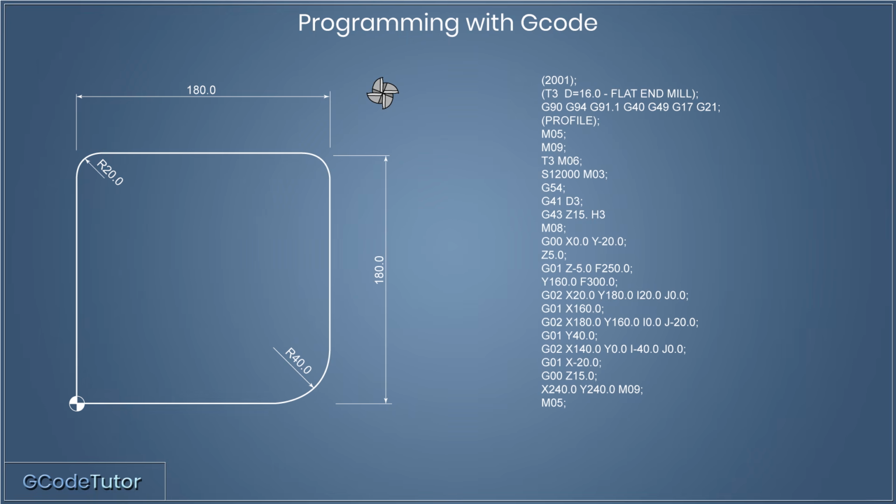Now that the cutter is back in its home position, we need to turn it off. So to turn off the cutter, we use the M code M05, or we can shorten that to simply M5. So M05 turns off the cutter. Because we used cutter compensation on this component, where we defined G41 earlier on before we started moving, we now turn that off with G40. So G40 turns off cutter compensation.